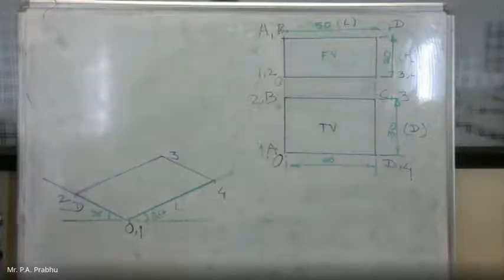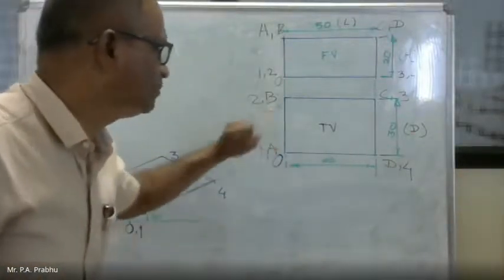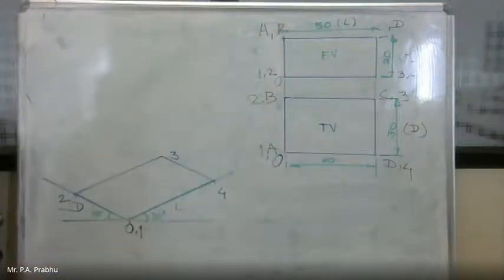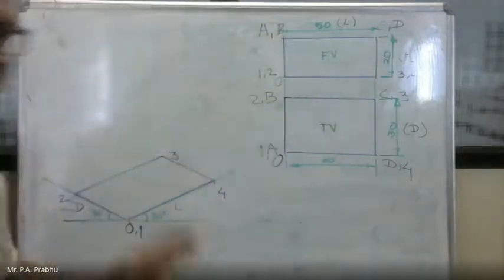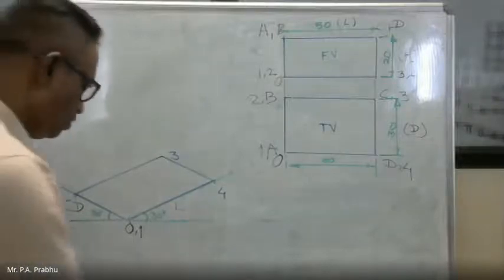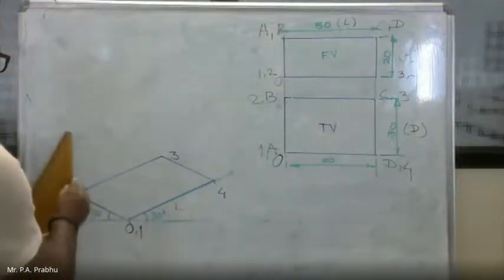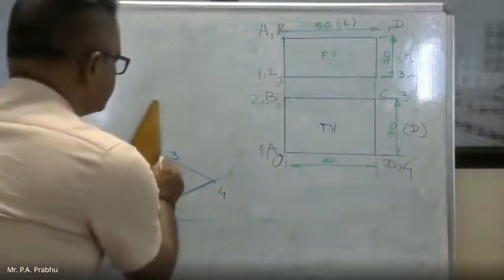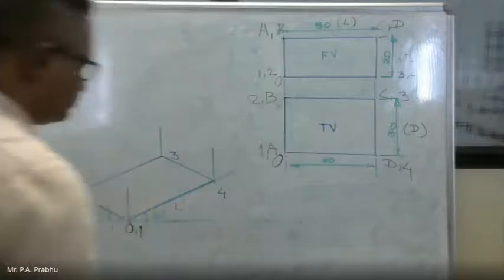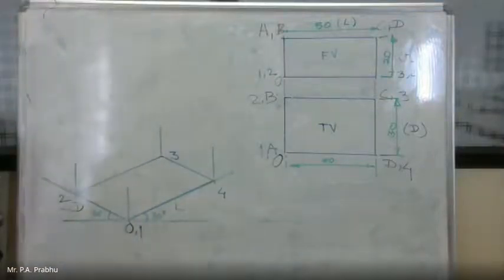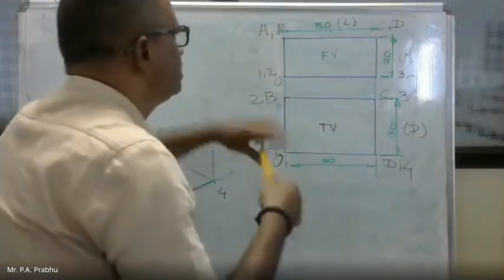Okay, so I have marked this width or length, and this is the depth. Now see in the front view. The height is 20 mm through each corner, 1, 2, 3, 4. Height dimension remains as it is. So through all these 4 corners, draw vertical faint lines, as the height dimension always remains vertical. Then the height is how much? 20 mm.